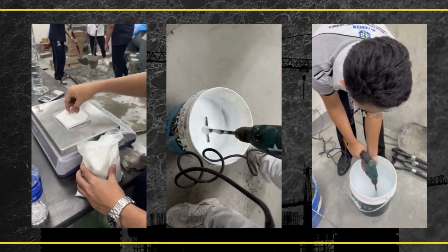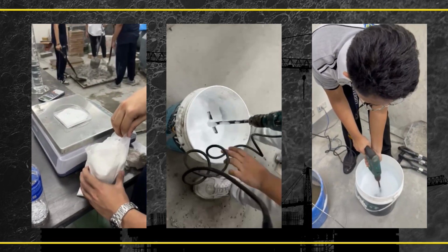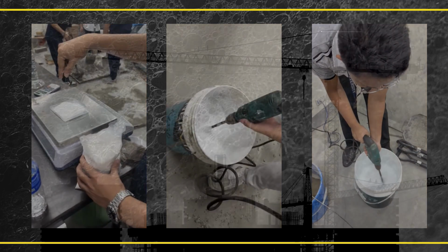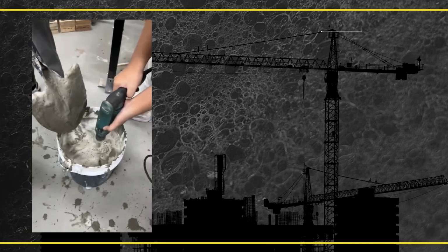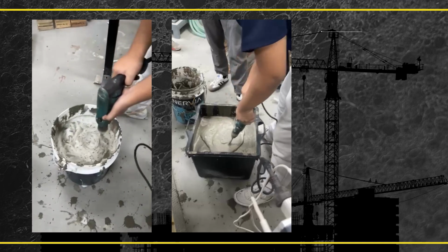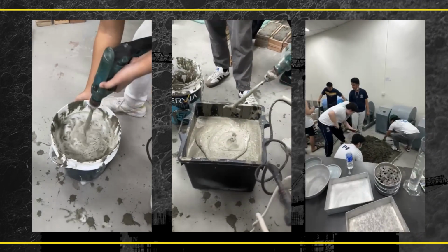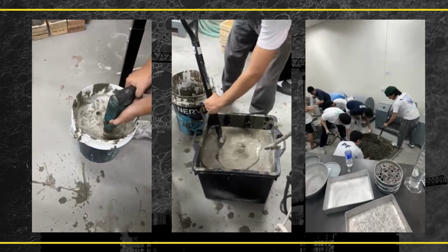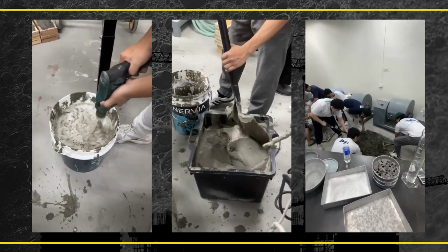This process produced stable foam with consistent bubble formation, which is essential for achieving the target density levels of the foam concrete. After foam generation, it was carefully combined with the dry mix using a folding and blending technique to prevent collapse of the air void structure. Proper handling at this stage is critical, as excessive mixing can significantly affect the material's final density and strength.